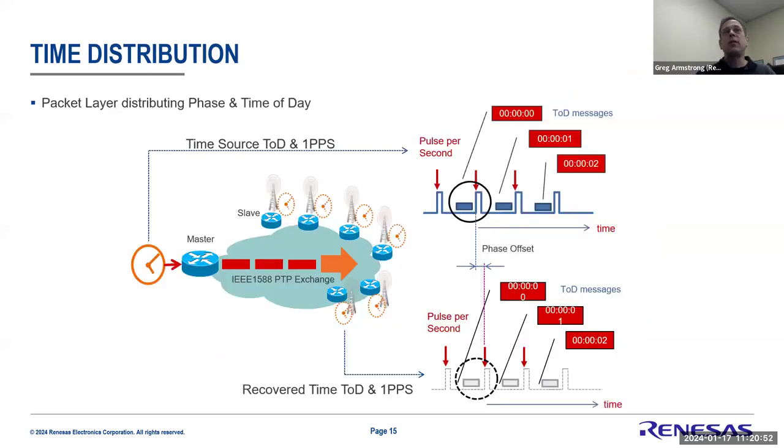And so, that's where a lot of these time distribution protocols come from. It was just because the reality is, looking at just trying to distribute a 1 PPS and TOD, although conceptually very simple, you could just use a simple coax cable to do that, it became very difficult to use that as a signal to synthesize or regenerate frequency components out of that. And so a lot of times it was much easier to look at protocol-based mechanisms.